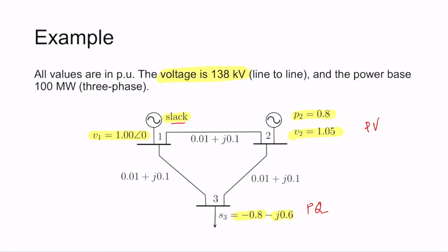We observe as well that these values of power are close to 1 because we have transformed everything per unit. The power base is 100 megawatts. Finally, the characteristics of the grid is given by this impedance, and this impedance. You see here there is only just one number, so it means we are considering only a series element. There are no shunt elements for this line.